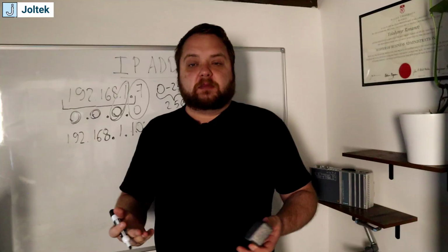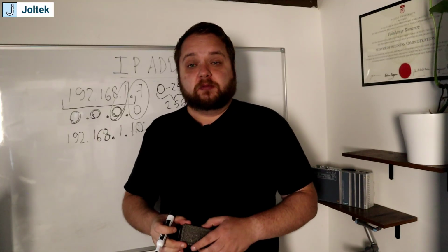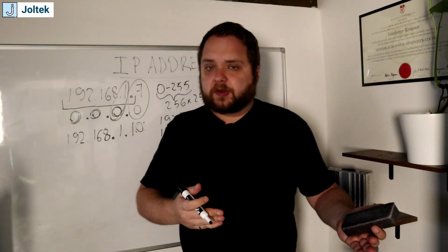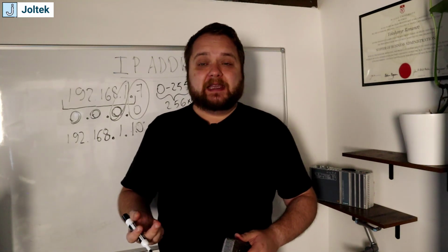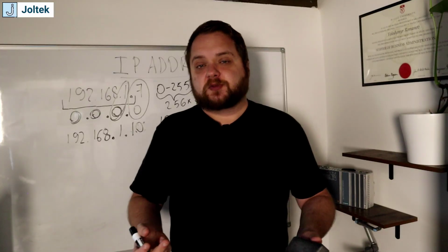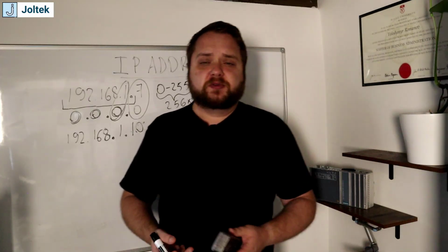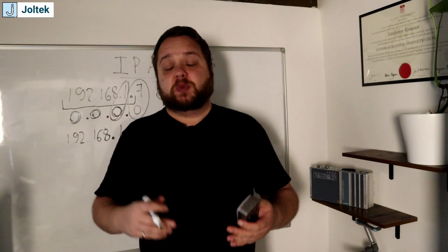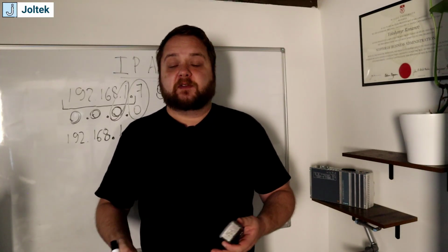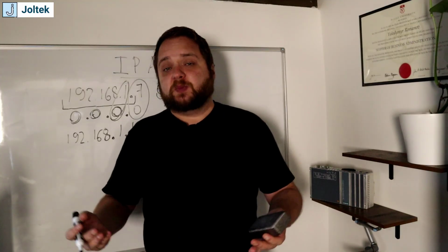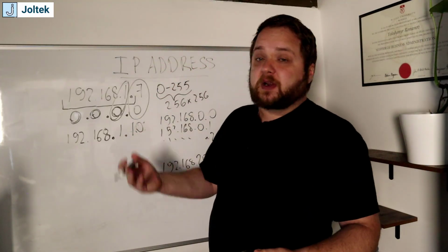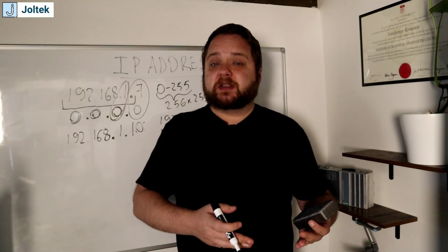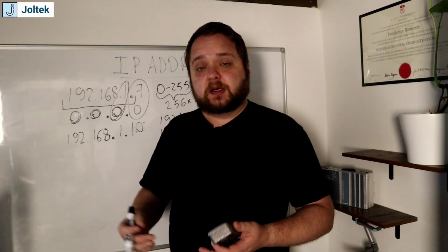And there's a couple of answers as to why you don't want to just have a vast number of devices on your network, including on the OT side. But number one is you're going to run into traffic issues, right? Depending on which hardware you're using, what kind of traffic you're sending, if it's motion traffic, vision systems traffic, or anything high speed, you're going to very quickly run into different bottlenecks.